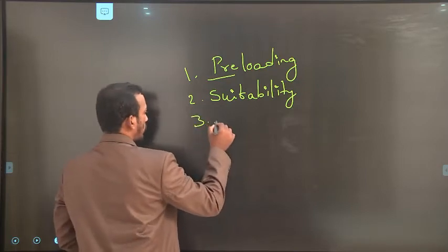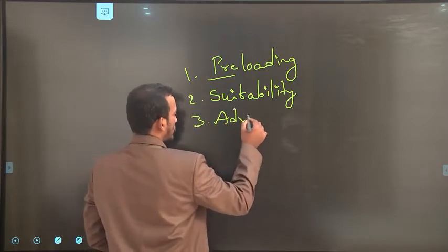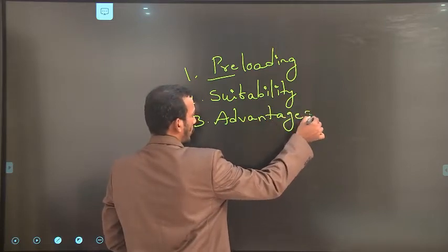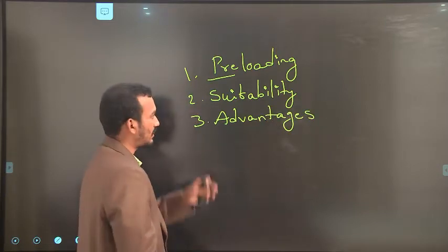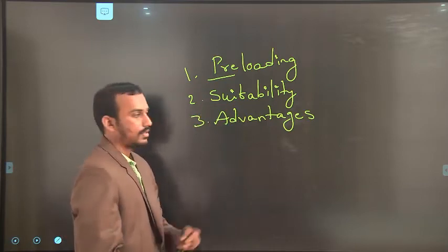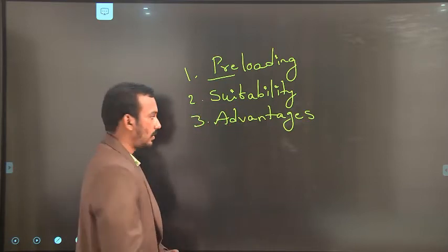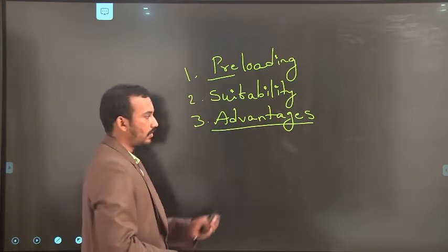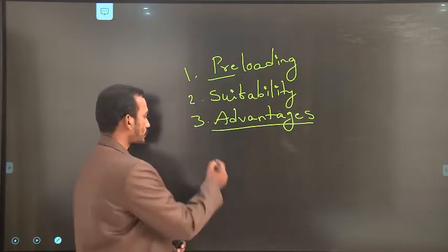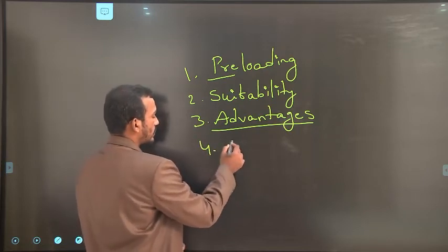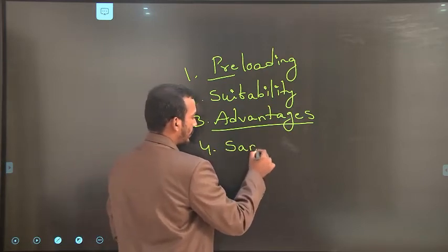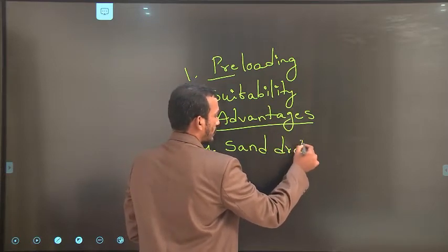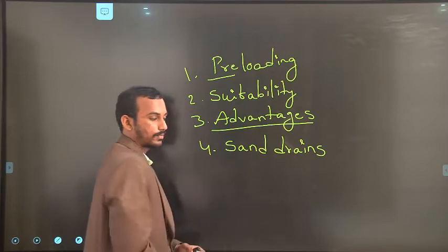Next, we learned about the advantages and disadvantages of preloading. The main disadvantage is that it is a time consuming process. And the advantages are that we are not applying any vibration forces and the cost is very less. And the next one is, the implemented method of preloading is sand drains. It is just an implementation of preloading.